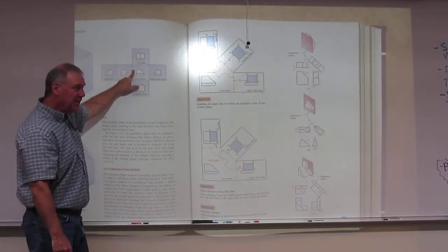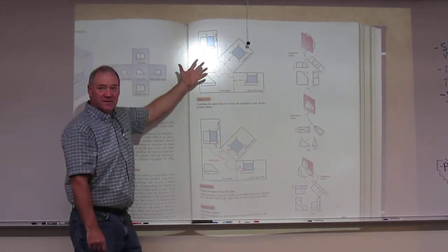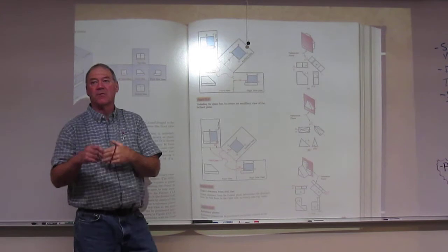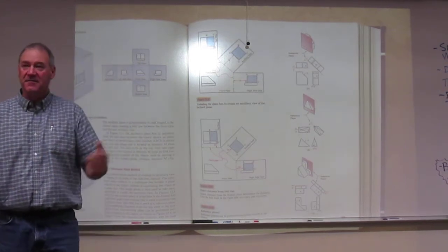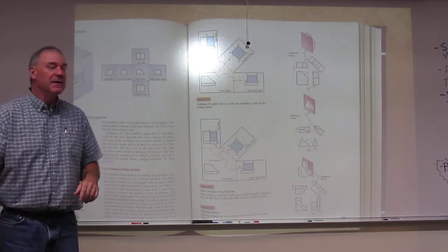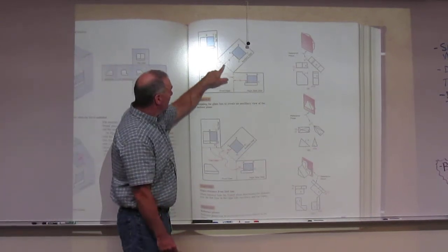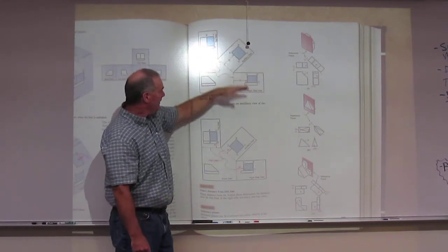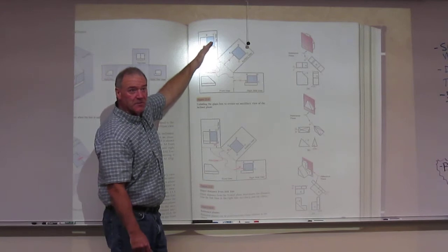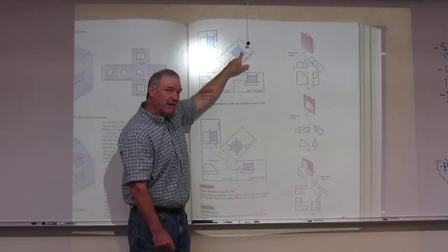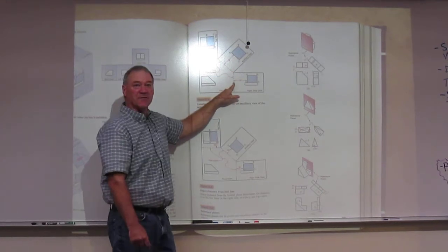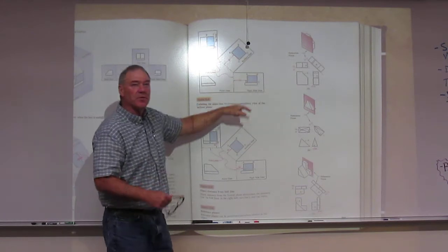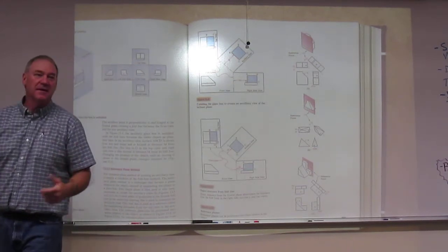But the fold lines represent where the glass box opens, and you can kind of see them right in here, same deal. Now, what we know about these when this object's sitting in this glass box is that it can't move in the glass box, therefore related views have the same dimensions and they have to be equal from fold lines through. So in essence what they're saying here, if I do a fold line on my auxiliary view, since this is a depth dimension, it is related to my right side and my top view, and the distance from this fold line to any feature of my auxiliary has to be equal to the distance from this fold line to any point in this feature. That's what in essence this is saying.